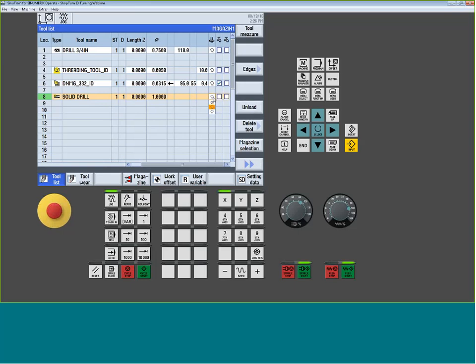So the big takeaway here is there can be some variance when you get to drilling when it comes to direction. The first thing I always recommend is certainly let's build a tool. Let's pick one of the two directions. Let's fire it up, and let's see if in fact things are spinning properly for this drill. If not, just flip to the other direction. There's a lot going on here as far as what's the main, live tool, non-live tool. So you always have to play this game a little bit. It's pretty common.